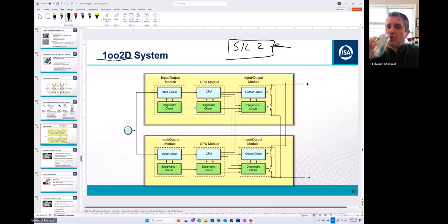Because the certification by a third party always adds cost to the project, is a self-compliant statement by the vendor good enough? Yes, but you, the end user, are responsible for what you install in the plant. So if you're saying that a device is compliant with 61508, it's your responsibility.